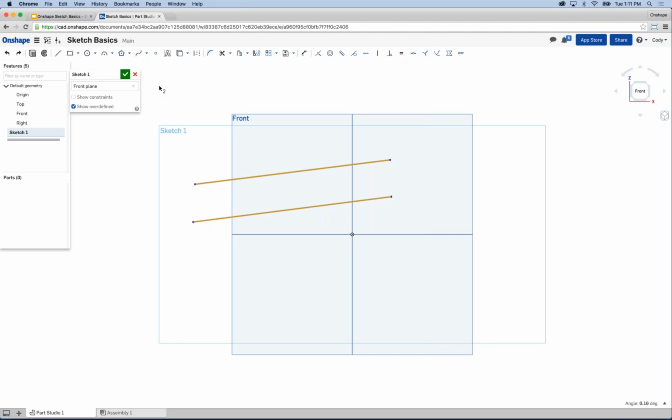Now the question often comes up, well, is there a difference if I drag right to left or left to right? And the answer is yes. If you have experience with other CAD applications, you'll know that the left to right drag versus the right to left will give you a different selection set, and that works as well in Onshape. But I just window selected those 2 lines, I hit the delete key, and now they're gone. Right? So it's easy to get rid of geometry if you no longer need it. So I have my lines, we've covered that.